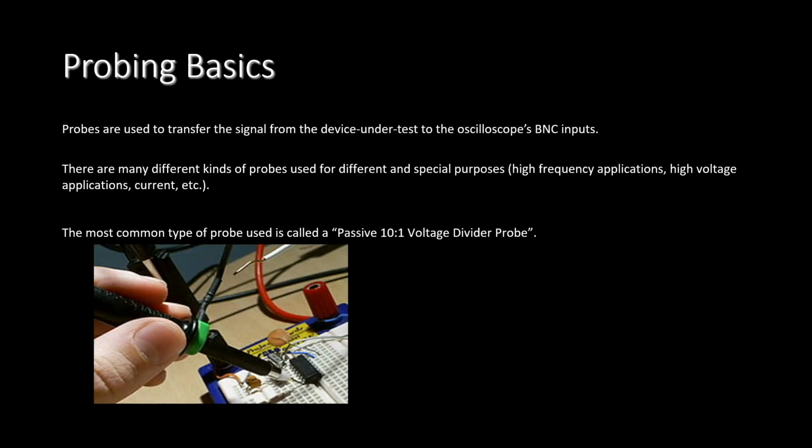Measuring an electrical signal on an oscilloscope requires getting the desired signal to be tested into the scope input BNC connector. If you want to measure the output of a generator, you would typically connect the output of the generator directly to the input of the oscilloscope using a standard 50 ohm BNC or SMA cable. Well, if you want to measure the characteristic of a signal at a point in your circuit, you would typically achieve this using an oscilloscope probe.